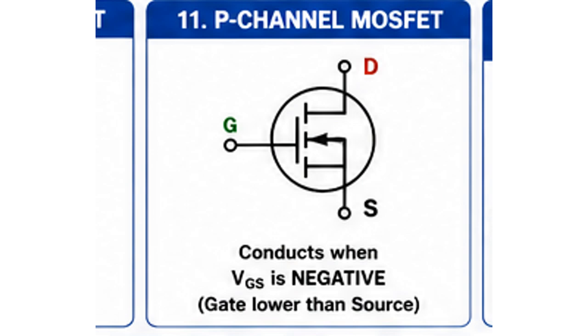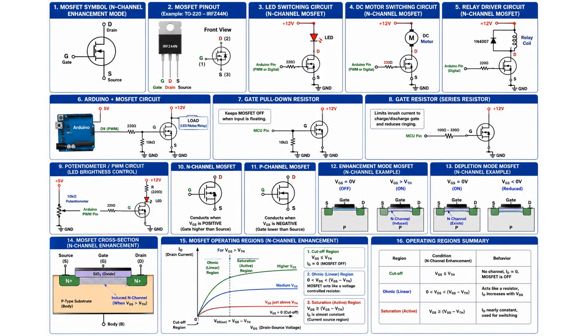When an Arduino or other microcontroller drives the MOSFET, 2 resistors are recommended. A series gate resistor between 100 and 330 ohms limits the instantaneous current that charges and discharges the gate capacitance. This reduces stress on the microcontroller pin and can dampen ringing that might otherwise produce electromagnetic interference.